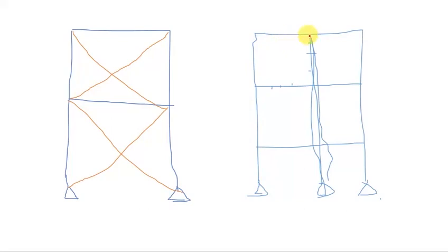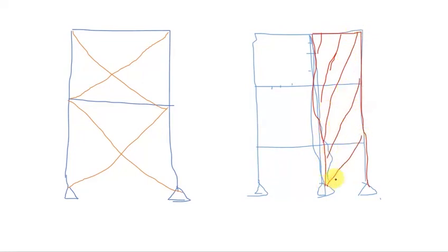You find a concrete wall called a shear wall running from the foundation, and it is going all the way up, right? So this is the shear wall. In concrete structures, this is the bracing, because it is the one taking care of the lateral loads.